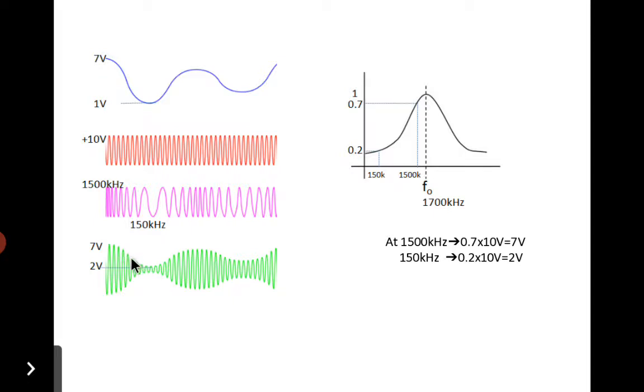So this signal is given to an envelope detector where we get the envelope of this AM signal as the message signal. Now this tuned circuit has a disadvantage, a problem. That is, this circuit is a non-linear circuit. Due to this non-linearity, we get some form of error in the output signal.